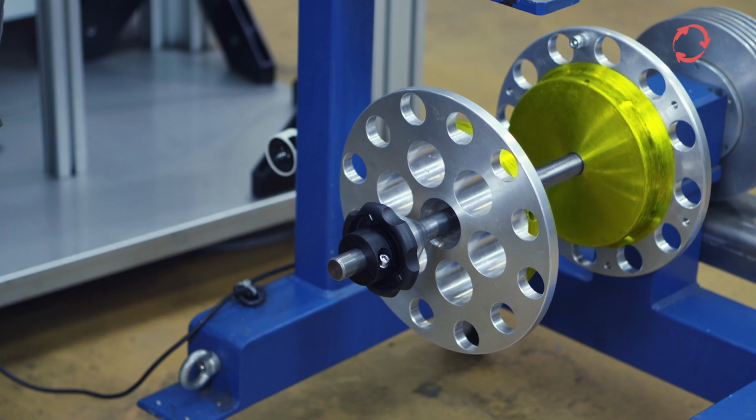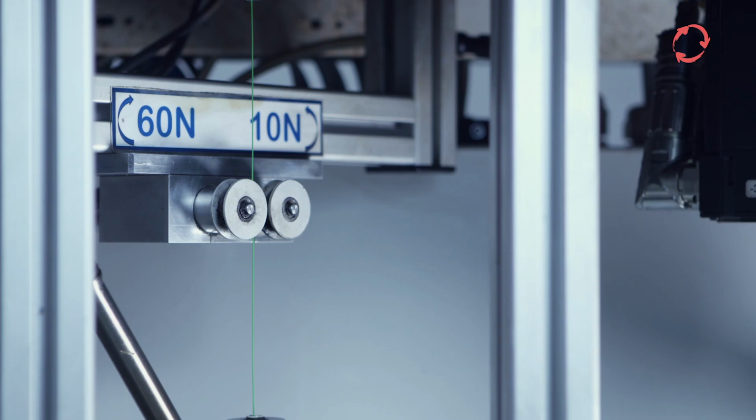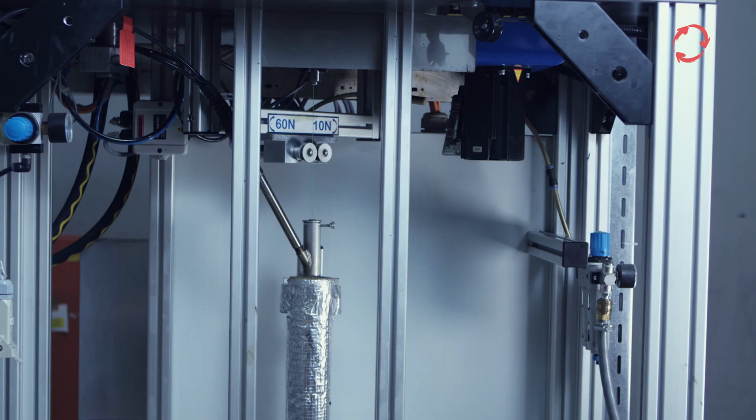In order to ensure error-free operation, the following cleaning work has to be done at least weekly. Clean, if necessary, the coil clamping rings in the tangential unwinder, the deflection rollers, the guide rollers on the thread tension sensor, and the interior of the machine.